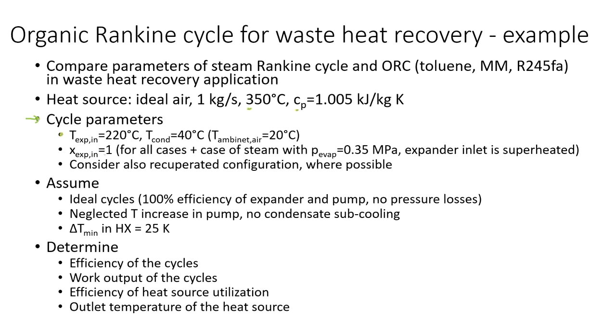Also, at the turbine inlet, we will consider the steam to be at the saturated vapor line, except for one case, which will be the water steam with given evaporation pressure, and therefore the expander inlet will be a superheated vapor. Also, for the organic Rankine cycle, we will see what the parameters will be when recuperation is applied.